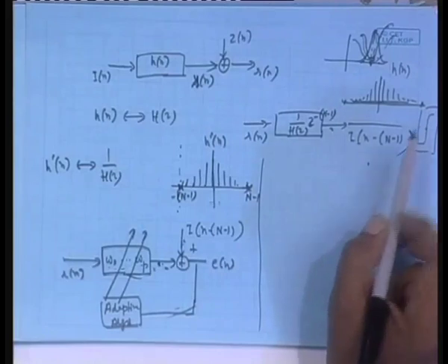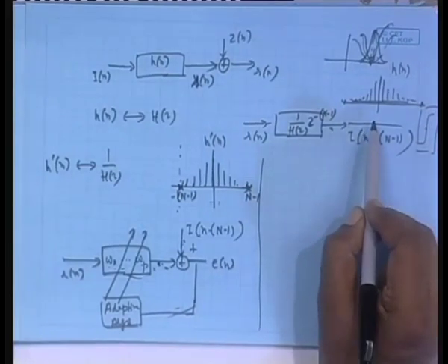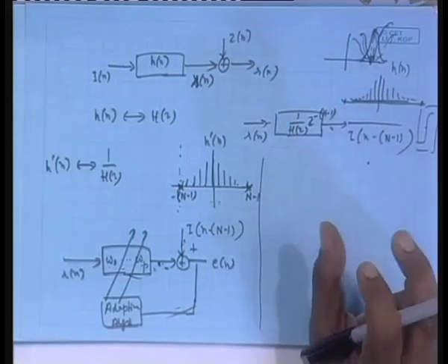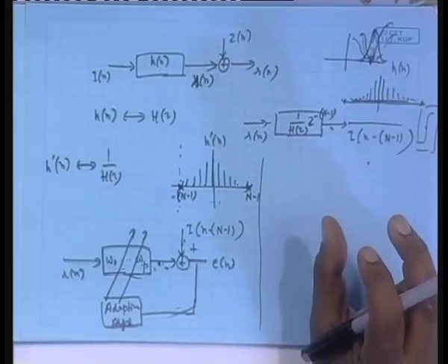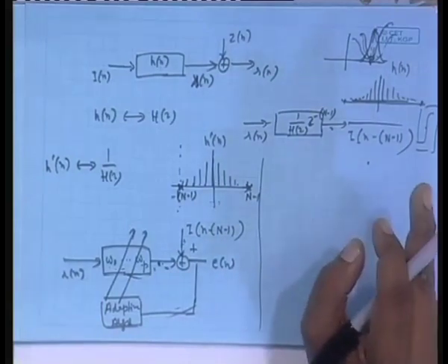Discrete values, like some various levels, 1 volt or 2 volt or 3 volt or 4 volt, like that. So, if you have a quantizer like that, and suppose indeed it is 1 volt, but because of noise it has become 1.1, still between 1 volt and 2 volt there is a huge gap. So, you can still make a correct decision.